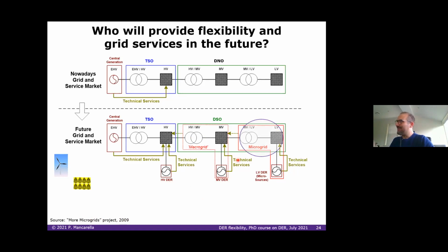renewables coming into the system, including at the low voltage network, so PV particularly, as we're seeing now, and to some extent batteries, the potential of having microgrids. And here microgrids is not just isolated microgrids that could be disconnected from the system. Also, this idea of smart districts and community energy systems, we're seeing more and more, is part of this. By aggregation and control locally, and then by scaling this to whole distribution networks, you can start interacting at the interface with the transmission system.